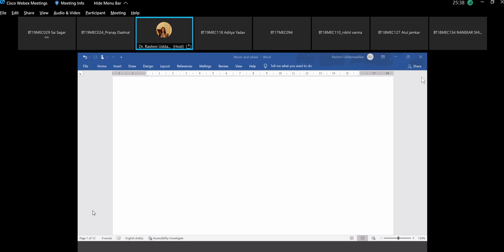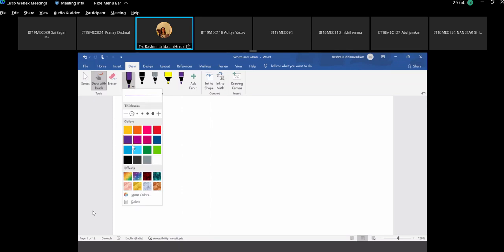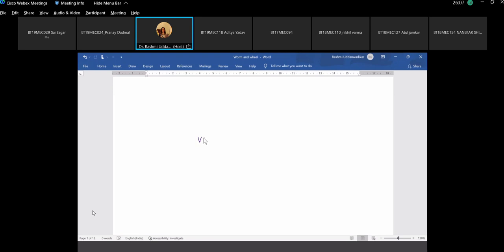What is the velocity ratio for worm gear, Pradyumna? Do you know? What is the velocity ratio range for worm gear? 60 to 100. It could be even higher than 100. If you have velocity ratio as high as 200 is to 1, 100 is to 1, 150 is to 1, the available option is worm and worm wheel, or worm and worm gear. Call it gear or call it wheel.